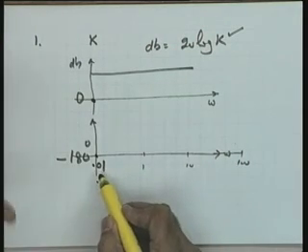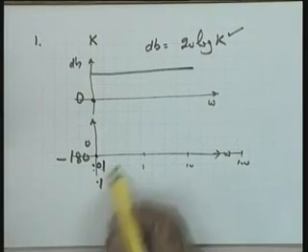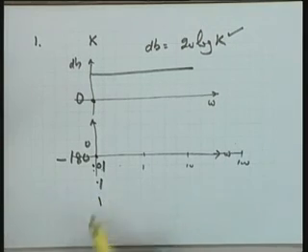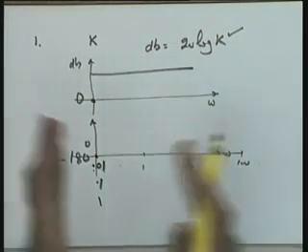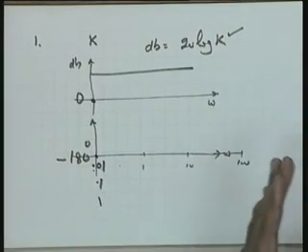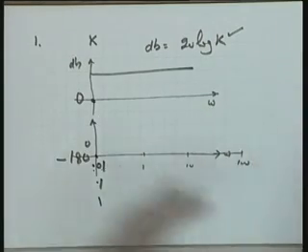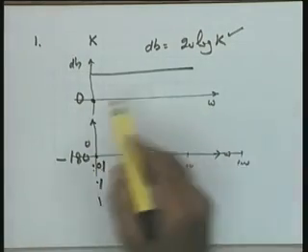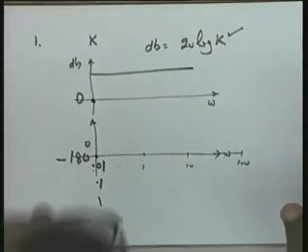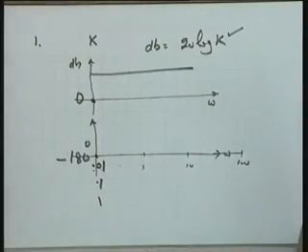So deciding this, you see, whether it is going to be 0.01, 0.1 or even 1, it depends upon the total high frequency range you want to study. So it means this is one important point when you make up your Bode plot. The appropriate decision should be taken right in the beginning.